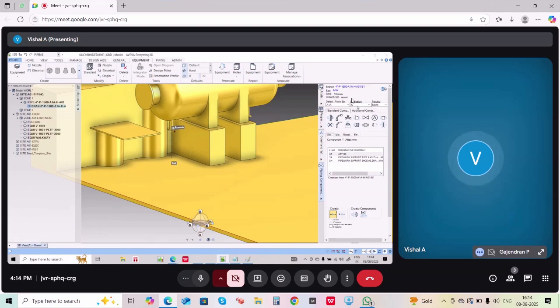Okay, insulation, tracing, everything is selected here already. Now, when you create the gasket, once you start the piping, the first component comes as a gasket. So this is your gasket. Now inside the gasket, you have two options, 150 and 300. Now how did this 300 come? This 300 is for the out of spec flanges or for a higher rating gasket. But for timing, we want only 150 and then just have to click create. So the gasket is created here.